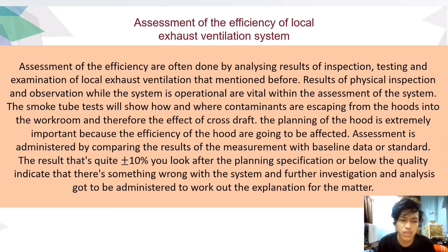The smoke tube test will show how and where contaminants are escaping from the hoods into the workroom and the effect of cross-draft. The design of the hood is extremely important because the efficiency of the hood will be affected.